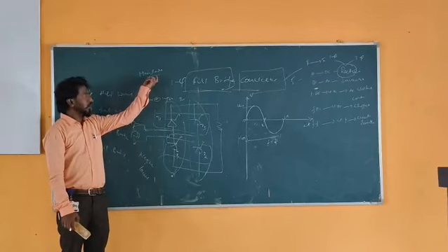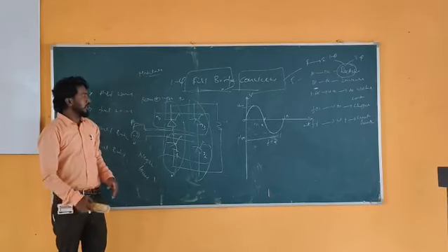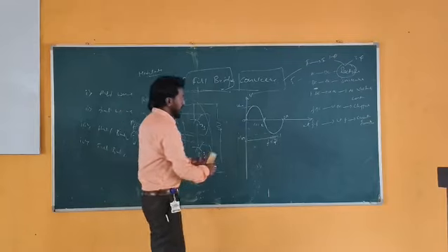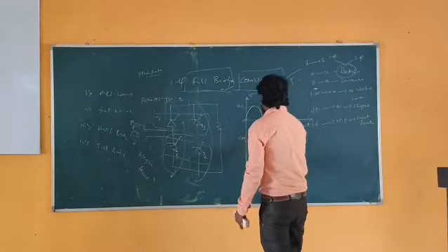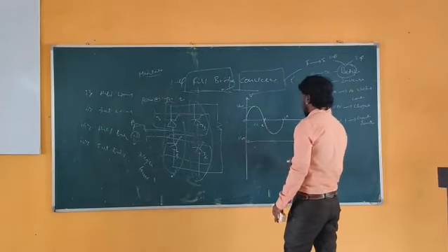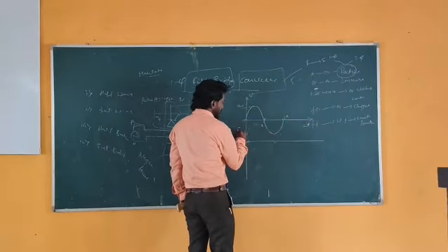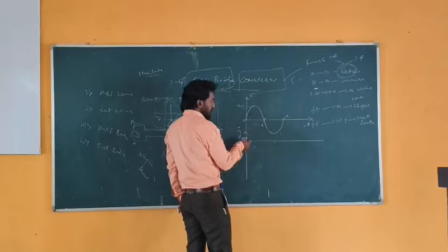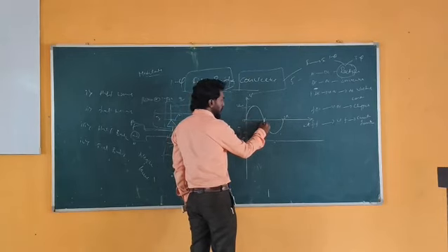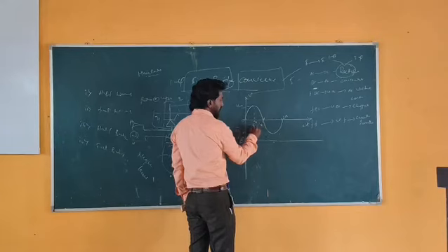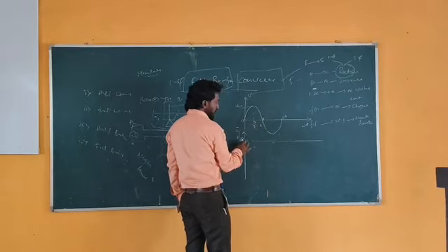And the gate pulse, we already know, we are generating from the firing circuit. So whenever we give the gate pulse at some delay angle, what is this delay angle? We can call it the firing angle, right? This we can draw as a gate pulse waveform, from 0 to 180 degrees, half of one cycle, which we can call pi, with 90 degrees at the middle.